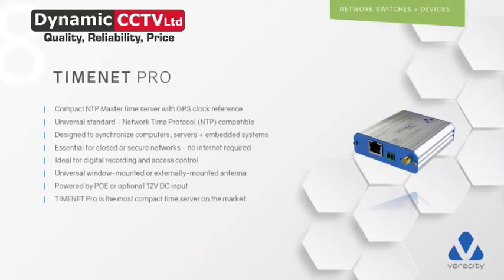Everybody needs a time server. Generally, you buy an NVR for cameras, whatever it might be, up to 1,000 cameras, it doesn't matter. These devices have got to get the time from somewhere. A lot of people won't use time, and then they get a mismatch. They have an incident, it goes to court, and gets thrown out of court because the time doesn't match.